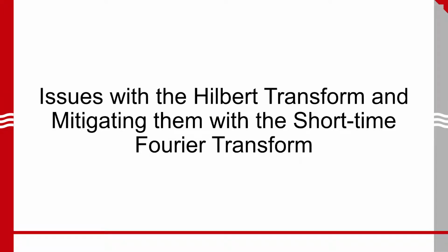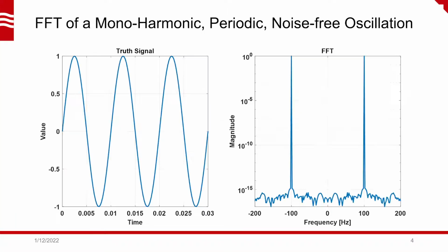First, I want to go over in more detail the issues with computing the Hilbert transform through the FFT and why we get ringing artifacts around any step change in the input signal. I think going over this does a lot to justify why utilizing the short-time Fourier transform is a very easy extension that minimizes many of the difficulties that come with trying to use the Hilbert transform.